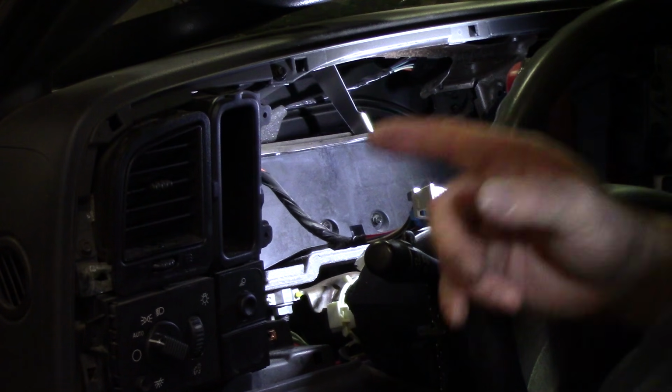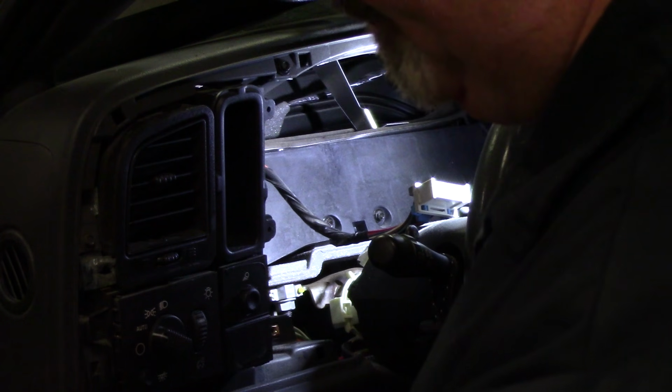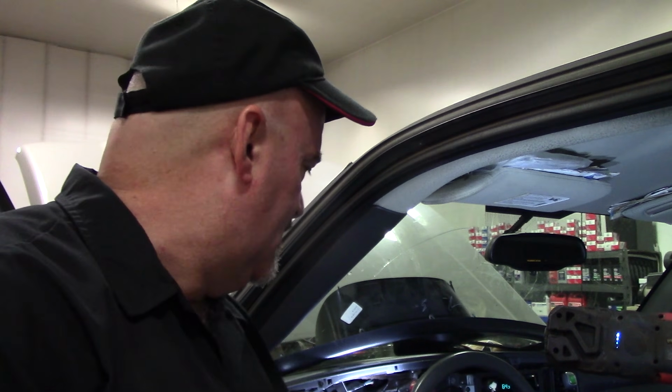So, looking good. You also want to pay attention to the connector itself. Those pins can loosen up in the connector, and that's a problem as well. A quick test for the connector is you can wiggle it when it's on the back of the cluster. If you just lightly wiggle the connector and you're getting intermittent function of the cluster, then of course you might want to take a closer look, see if your connector sockets have loosened up a little bit on the pins, and you could tighten those and square that away. But in this case, it's obvious we need a cluster.